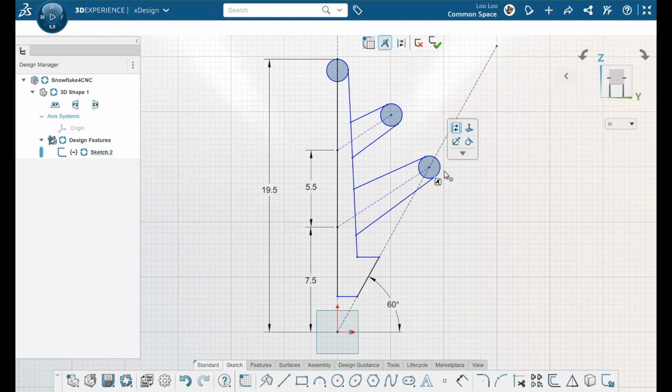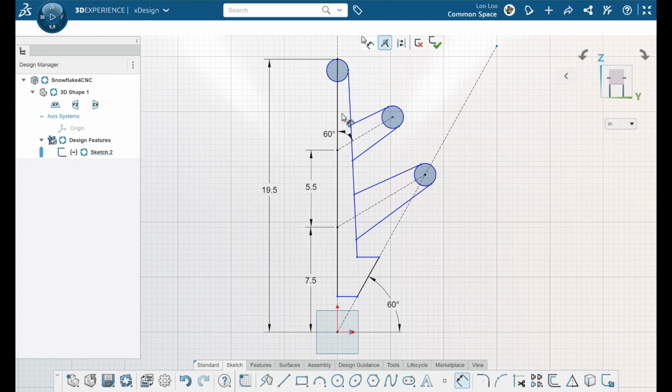Now, if I switch over to the dimension using the keyboard shortcut D, I can start laying out some of the angles between the spurs and the main leg. You notice as I make these dimensions, before I click again to place them, it's actually following my cursor as I drag around. Once you place them, you can drag them out away from the center of the arrows. So there are a few things you can do to properly position your dimensions.